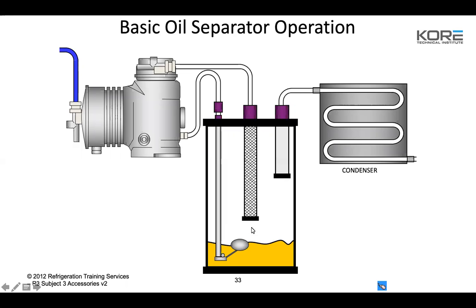And so what happens is this thing will just keep passing oil and refrigerant through the system. So you'll go to pull this cap off and it'll be empty, and you'll say, oh, well, we don't have any oil, so add a gallon of oil. What happens is this float needs to open and push that oil up, or it just keeps passing through the system.